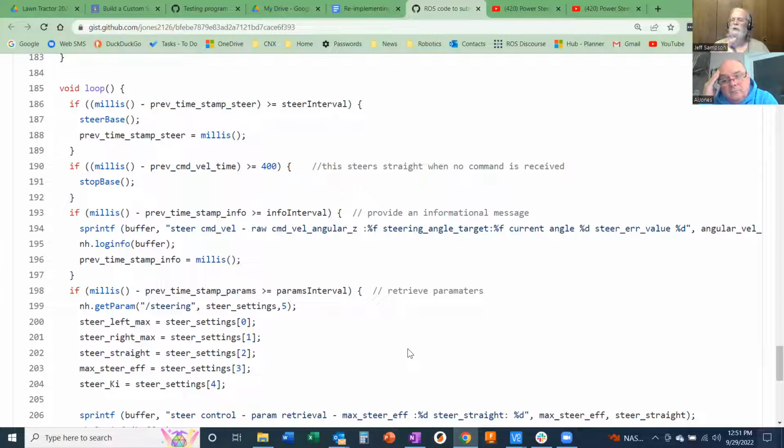And once it gets to that chip, it then turns into USB world, and now it sends out packets at 12 megabits per second back to the computer. So that part of it is very fast. I don't know how it organizes the packets or anything, but in general, that's a very fast interface. But on a regular Arduino, you're going to have a problem if you're putting out a big long line of text like that. You want to put it out as fast as possible so it doesn't waste any more time than necessary.